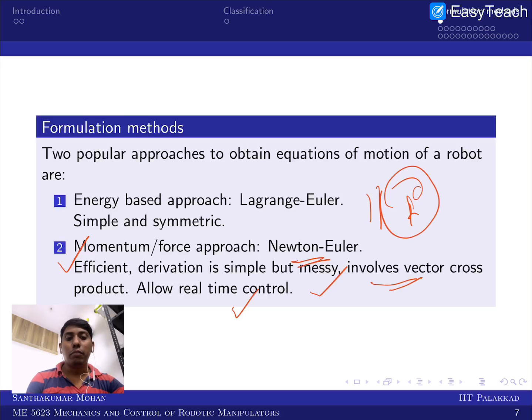important and what is the equation of motion, or in the sense what is motion dynamics. So what are the two subclassifications, or the two different mappings? One is forward dynamics, where for a given torque vector, we look for the motion variable. Whereas for a given motion variable and its derivative, finding the input vector is what we call inverse dynamics. So forward dynamics is nothing but simulating or analyzing the system, whereas inverse dynamics is very close to controlling the manipulator. And at the last slide where we stopped, there are several methods available.